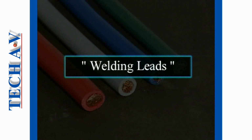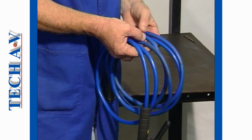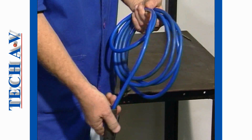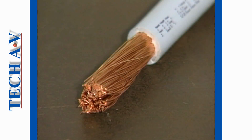Let us now look at welding leads or welding cables as they are usually known. Welding leads are made in such a way that they are very flexible, so that the welder is easily able to move them, yet heavy enough to carry the high amperages that are associated with welding. The construction of a typical lead is shown here. You will notice that the conductor core is made using many strands of fine copper wire, and it is because of this that welding leads are very flexible.